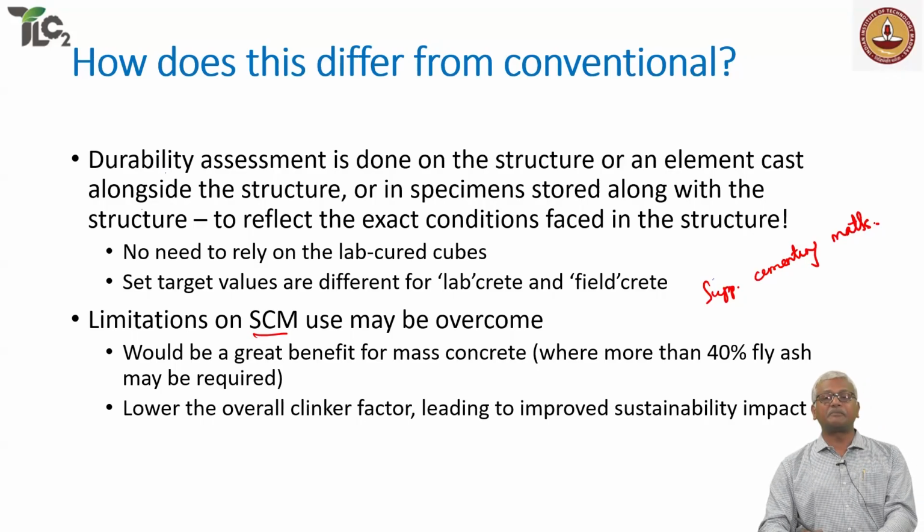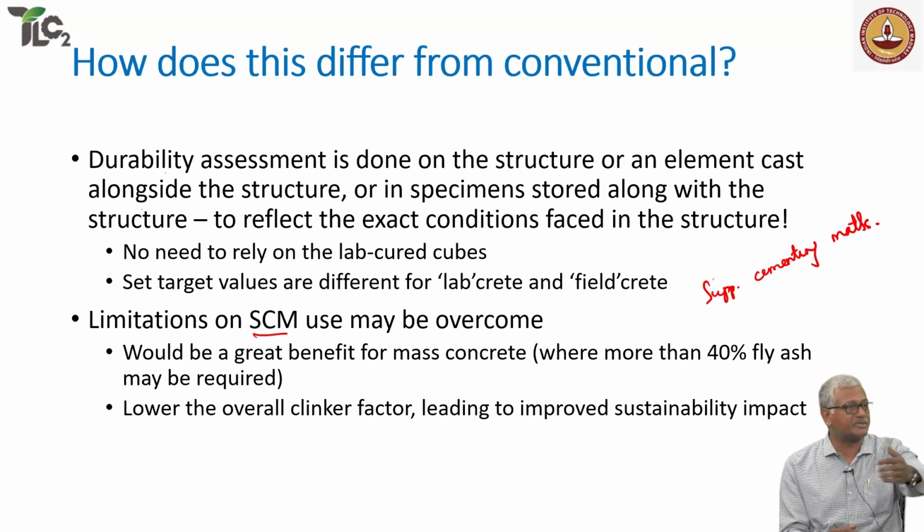The limitations of supplementary cementing materials can be overcome to a large extent. In many cases, we are bound by our codes saying that you can't use more than so much percentage of this, so much percentage of that, and so on, right? If you start following those prescriptions, we are very restricted in what we can achieve in the concrete.